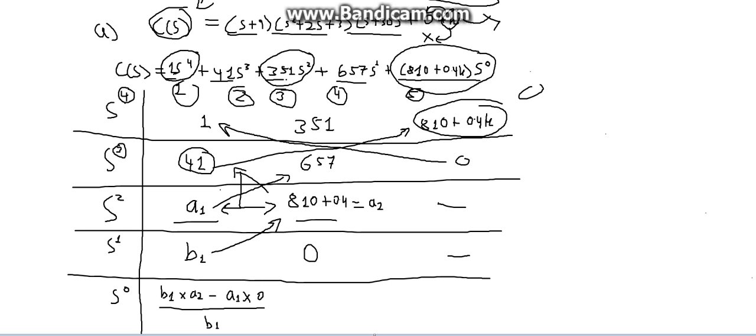So let's just call this C1 in the Routh criterion table. The denominator is going to be B1. You notice the B1 cancels with the B1. You don't even have a term here that's 0, and you're just left with A2, and A2 is this term here again. So you just throw this over here as C1. Try to memorize that A2 and C1 are going to be your constant value. This is your constant, same as this guy right here, constant. So memorize that, guys. It's important.